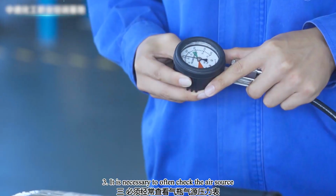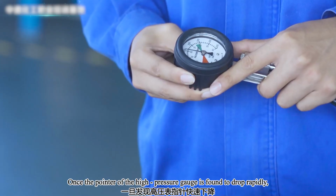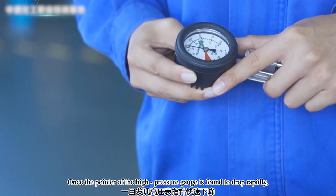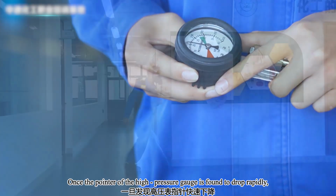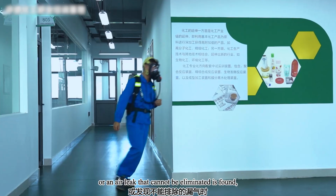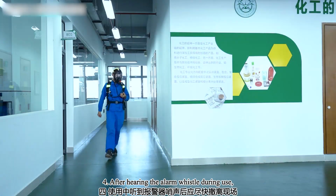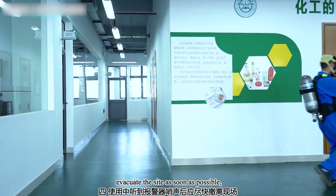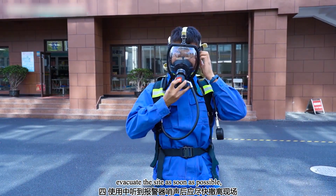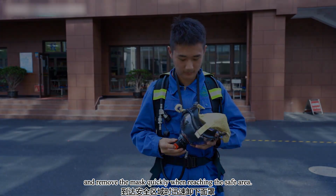Third, it is necessary to often check the air source pressure gauge of the cylinder. Once the pointer of the high pressure gauge is found to drop rapidly, or an air leak that cannot be eliminated is found, evacuate the site immediately. Fourth, after hearing the alarm whistle during use, evacuate the site as soon as possible, and remove the mask quickly when reaching the safe area.